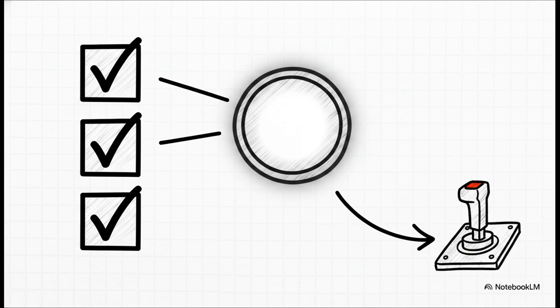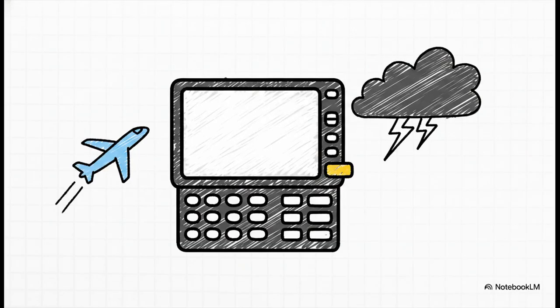Alternatively, depending on your specific setup, you can actually bypass the FMS menu entirely and just hit the physical go-around button. To make this stick when the workload gets heavy, just remember this effortless trick to cement the manual FMS sequence in your brain. Navigate 3 right out of danger. You're on the nav page, hitting the third key on the right. Simple, super effective, and it takes all the guesswork out of the equation.